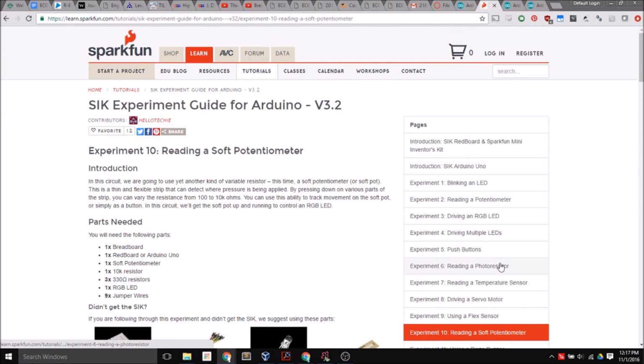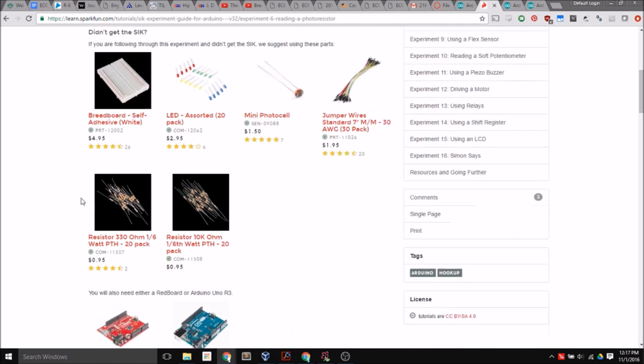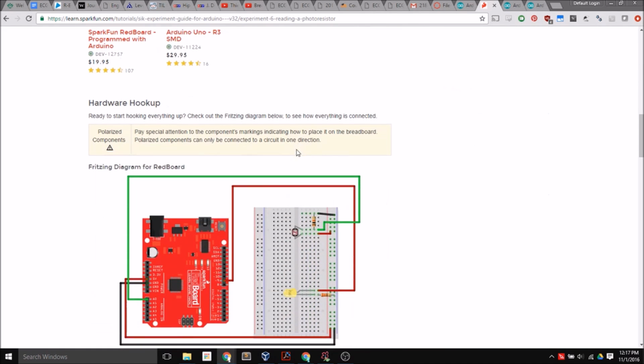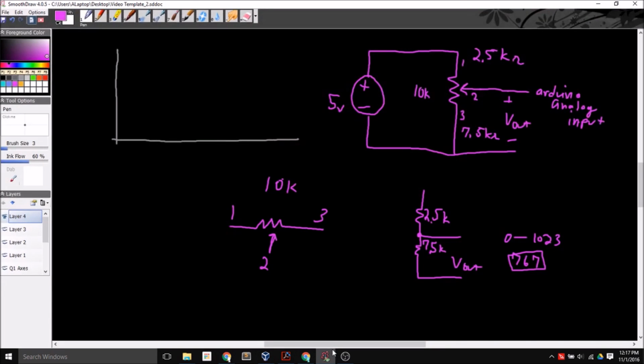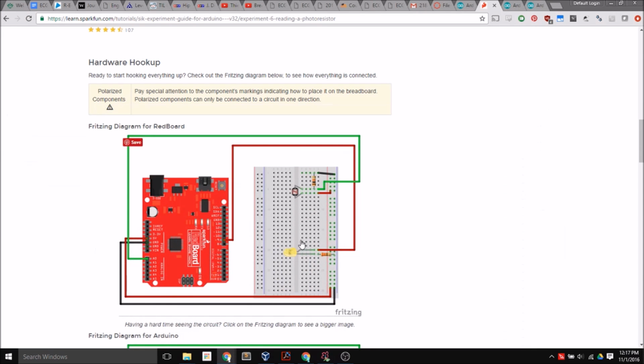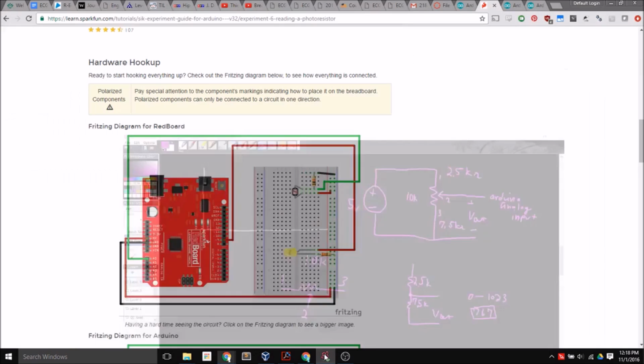Again, you could also read a photoresistor. And so this is a photocell, and the resistance changes based on the amount of light hitting that photocell. And so if we replace our potentiometer with this photocell and a reference resistor, and again that would look just like this part. This is our reference resistor and this would be our photocell, for instance. We can use the same code as our potentiometer. We read in my analog 0, and then I'm going to flash my LED at different frequencies. And so try these out.